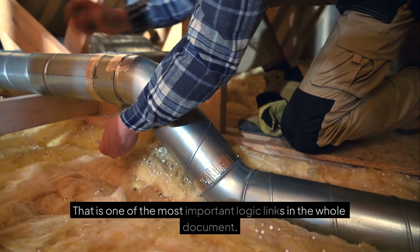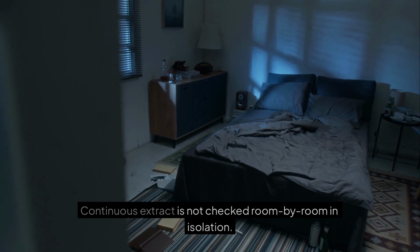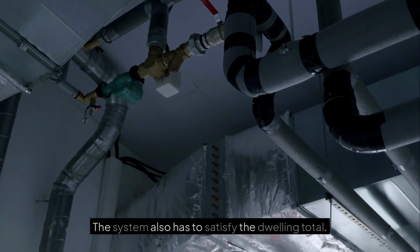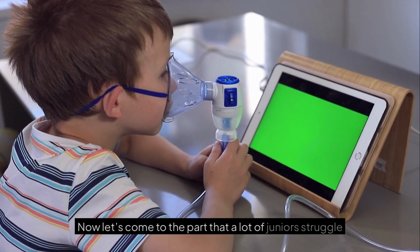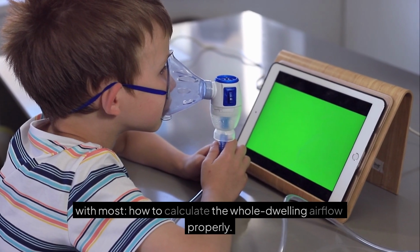That is one of the most important logic links in the whole document. Continuous extract is not checked room by room in isolation. The system also has to satisfy the dwelling total. Now let's come to the part that a lot of juniors struggle with most: how to calculate the whole dwelling airflow properly.